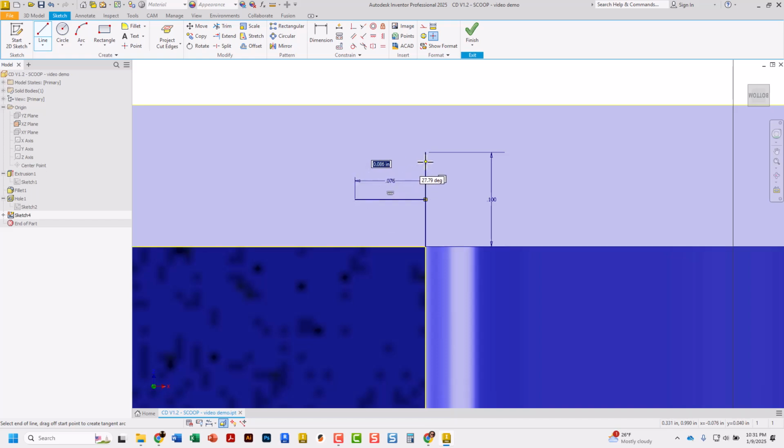And now I'm just going to rough in the two angled lines, like so. Notice they do not go quite to the end of the 0.1 line. They should stop a little bit short, and we are going to dimension exactly where right now. So from point to point, I want a dimension of 0.00625. Do that on both sides. 0.00625.